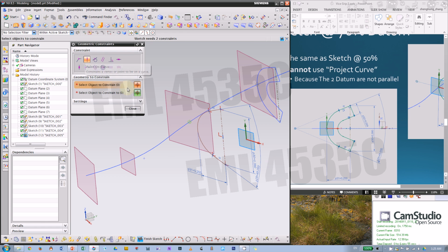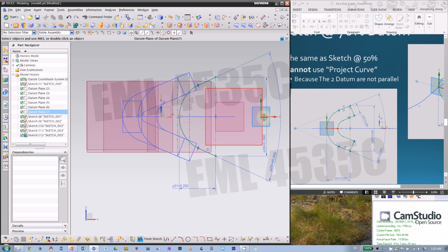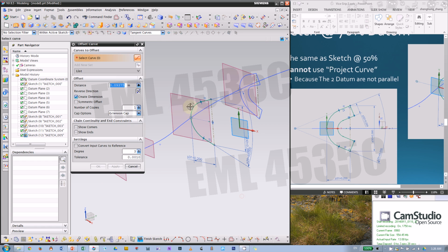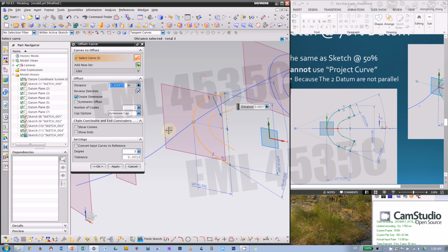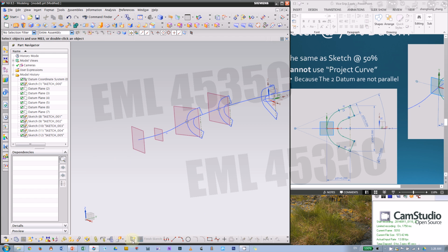First, you want point on curve. Okay, I want this arc to be on this point, and next the midpoint. So I want the reference as a midpoint of sketch origin or the intersection point. It's the same. Okay, that intersection point is definitely on the x-axis, as you can tell from here. Okay, now that outside C is finished, offset the same distance, the same curve method. Let's click here, reverse, then close this up. Finish, and next.